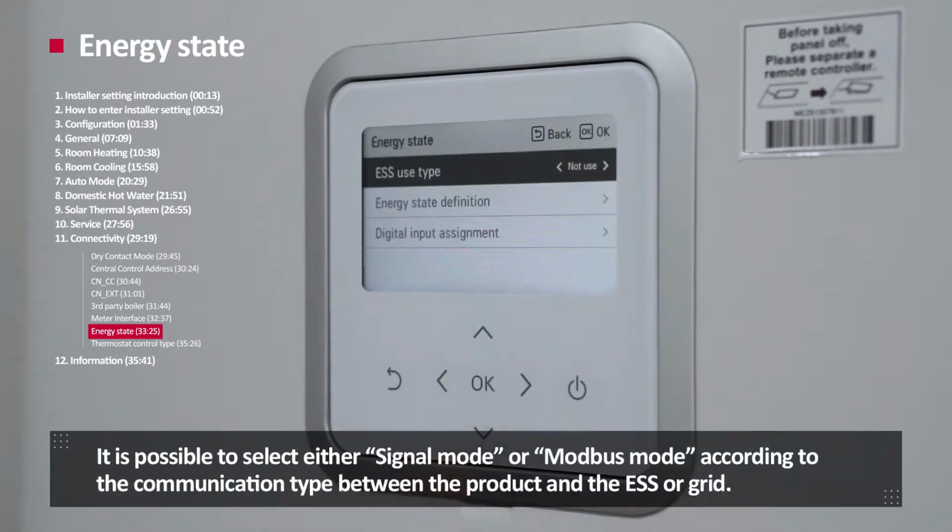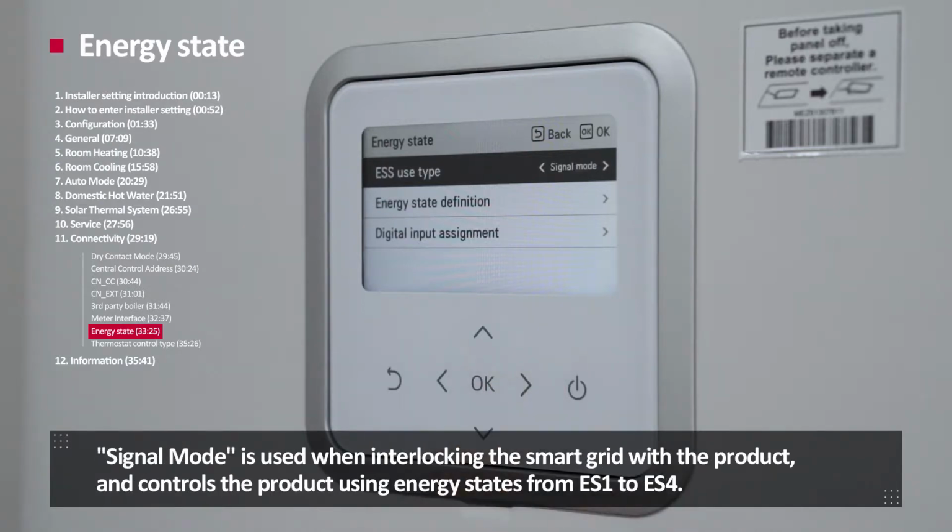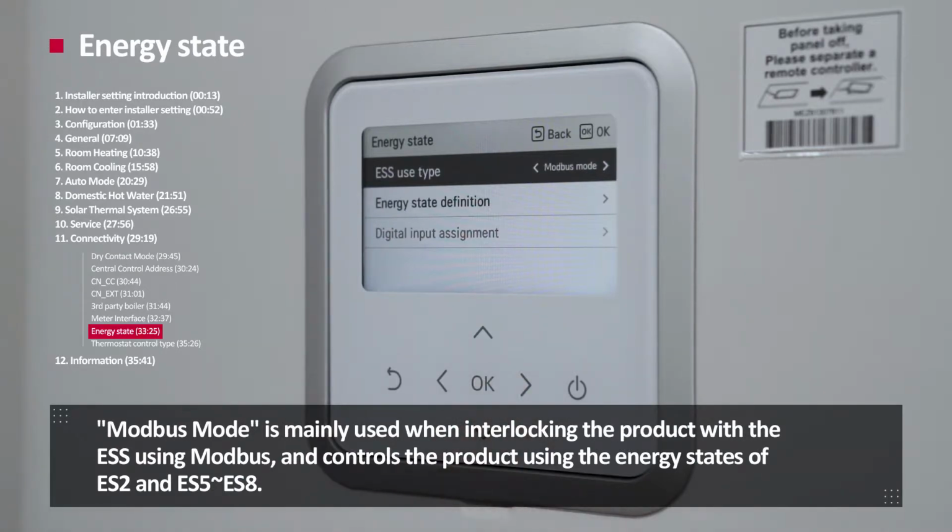It is possible to select either signal mode or Modbus mode according to the communication type between the product and the ESS or grid. Signal mode is used when interlocking the smart grid with the product and controls the product using energy state from ES1 to ES4. Modbus mode is mainly used when interlocking the product with the ESS using Modbus and controls the product using the energy state of ES2 and ES5 to ES8.